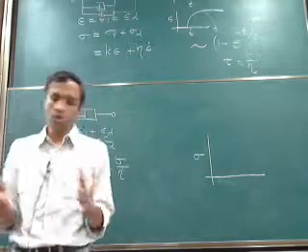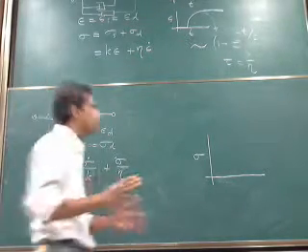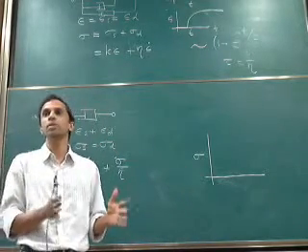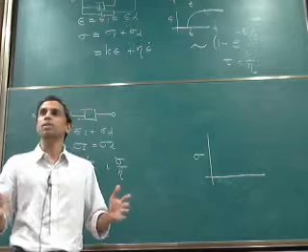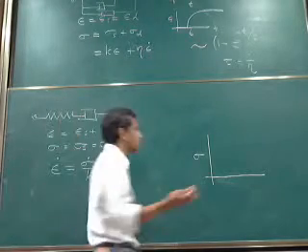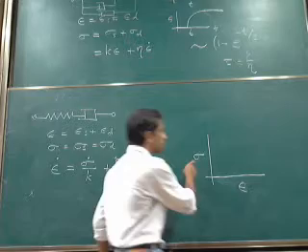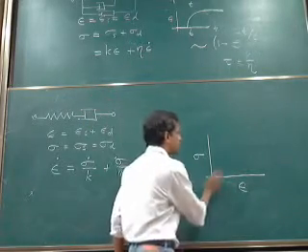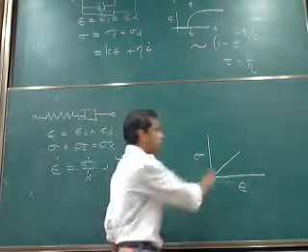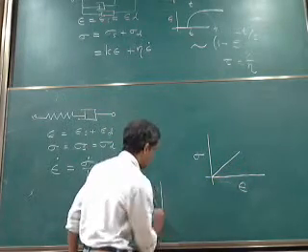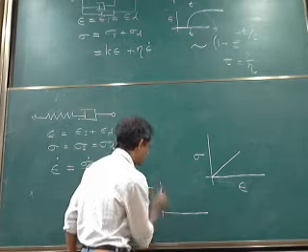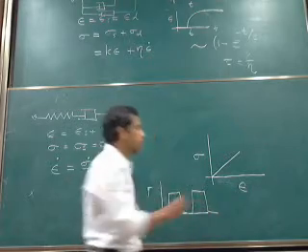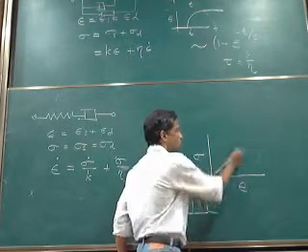If I have a solid material, often I cannot deform it by very large amount. Okay, and I don't want to deform it by a very large amount because I want to be within what is called a linear regime. Okay, if I deform it by a very large amount, other things happen. It can yield, it can flow, and other complications. So I plot stress versus strain. If I have a Hookean material, then this will be a straight line. Okay, and if I cycle it, my force, I'm cycling like that, then I keep going back and forth along this line.